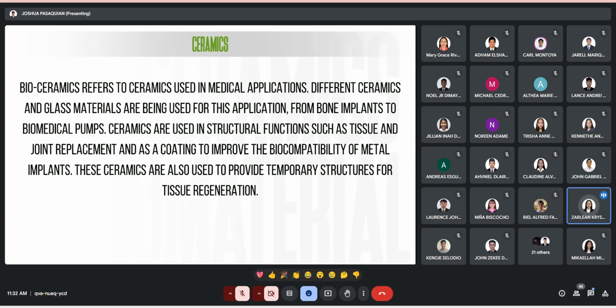With that, we can conclude that polymeric materials can be used to enhance the stability, increase the target-specific delivery of drugs and genes, optimize the pharmacokinetics and biodistribution, and reduce the side effects and improve the efficacy of the system. Some of the polymers used for implants are biodegradable in the body. This is one of the advantages of using polymers as biomaterials. But know that polymers are not as stiff as metal or ceramic, so these materials are not advisable to use if the implant is required to carry large loads.